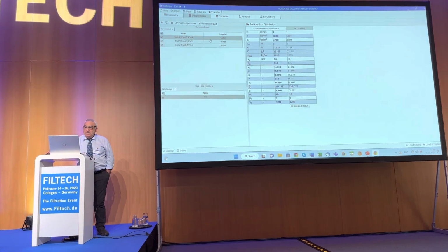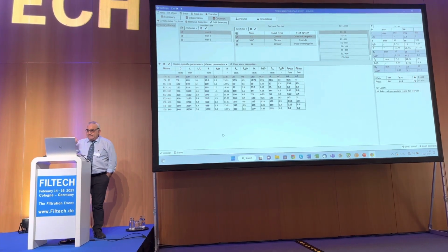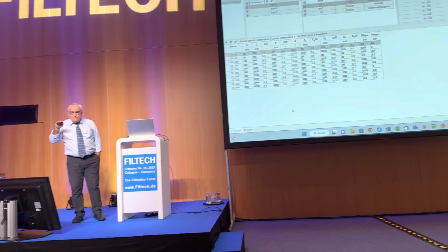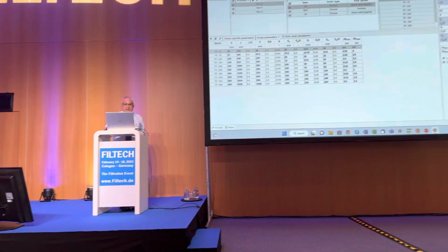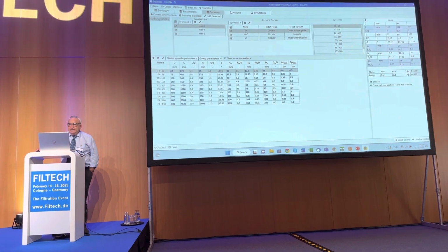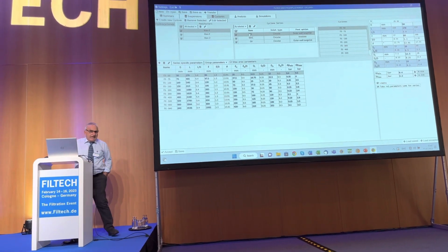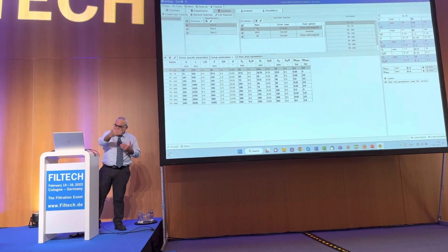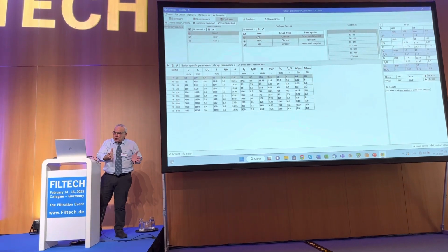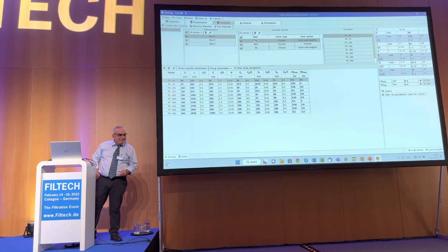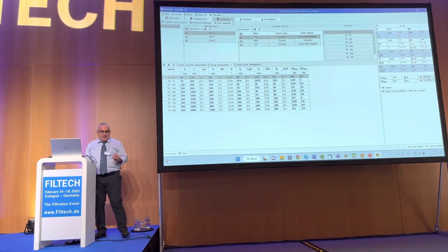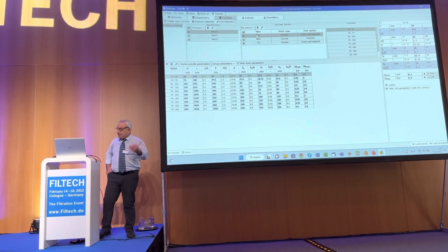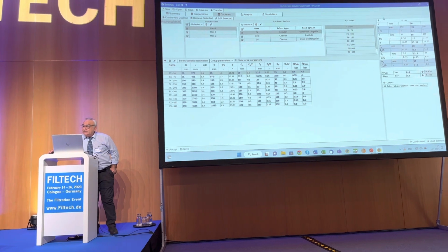You have also the cyclone database. Here you can enter the geometrical data of any hydrocyclone of any manufacturer. You can see here is a filter based on manufacturer, and here you see the name of the cyclone series. The cyclones, of different diameters, belong to the same family or to the same series if approximately the relative parameters are the same. And this is assuming that cyclones belonging to the same family have the same specific parameters.